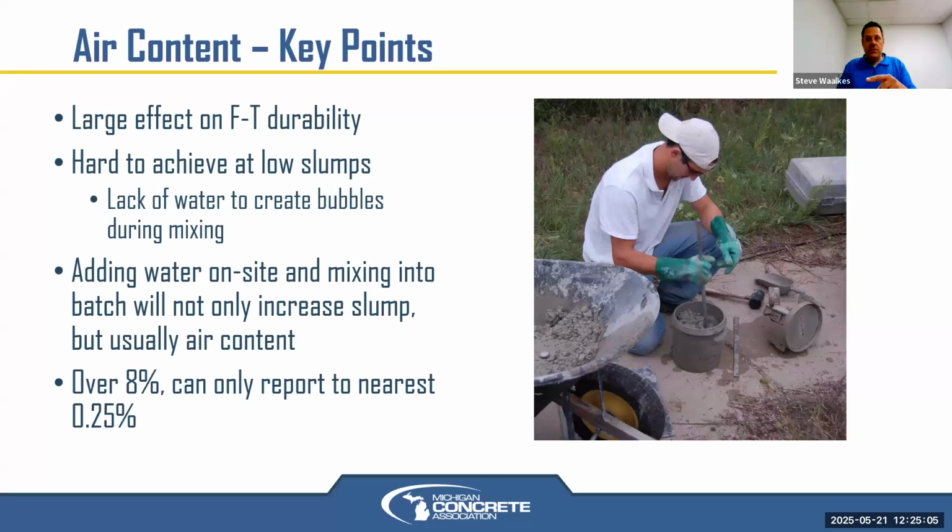Well, if you have the air entrainment admixture in the mix but you don't have a lot of water, and then you add water on site and remix it 30 revolutions in a ready mix truck, you'll actually be creating air. Not only are you increasing the slump by adding water to that batch, but you're also going to be increasing the air because the chemical's already in there. So that's a good thing to remember. If you're adjusting water contents on site, air may come along with it if it's an exterior mix that has air entrainment in it.